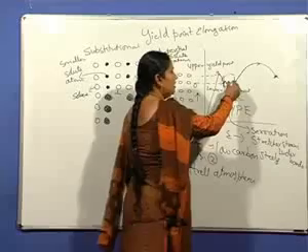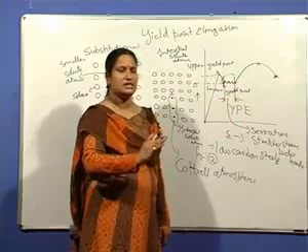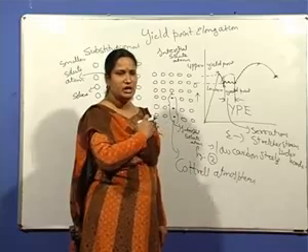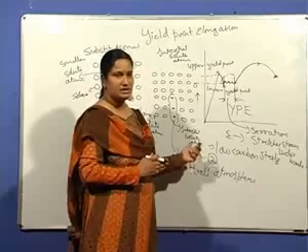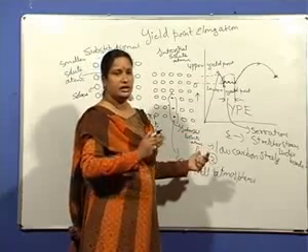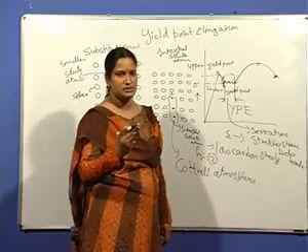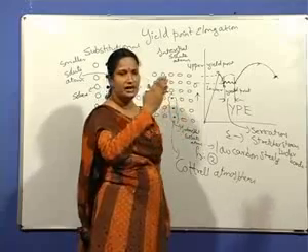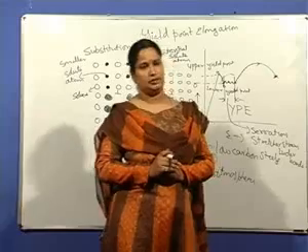So at this point, the material follows the normal stress strain curve because the dislocations are completely torn away. That means they have completely crossed the barriers. The barriers are the interstitial elements, carbon and nitrogen. They're completely torn away from these quaternary atmospheres. So normal strain hardening is seen, and finally the curve follows the normal curve.